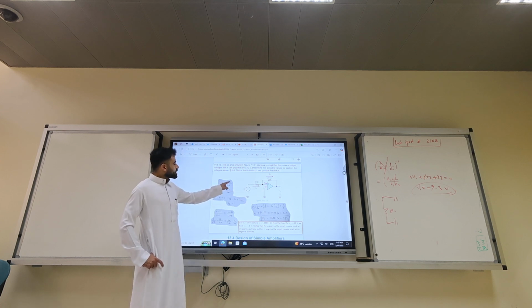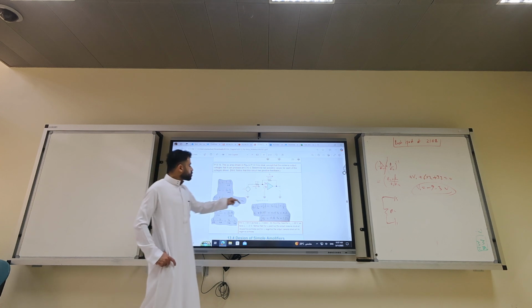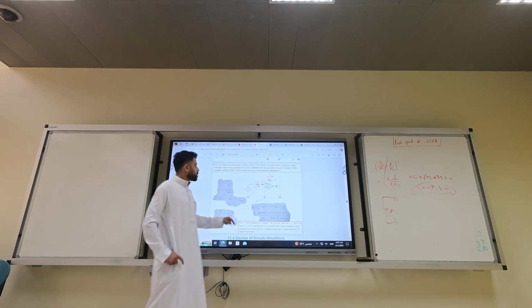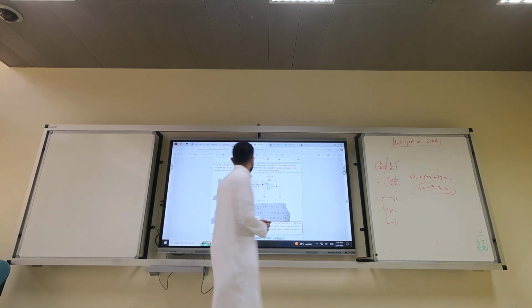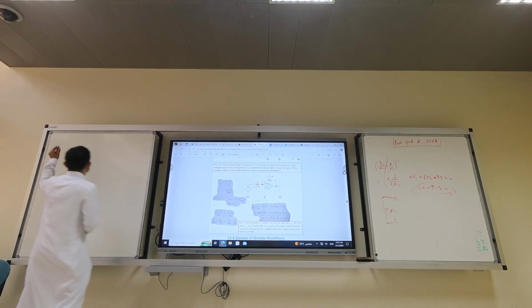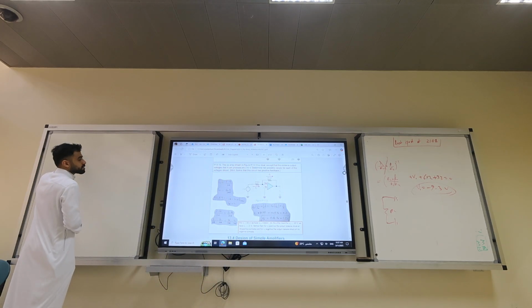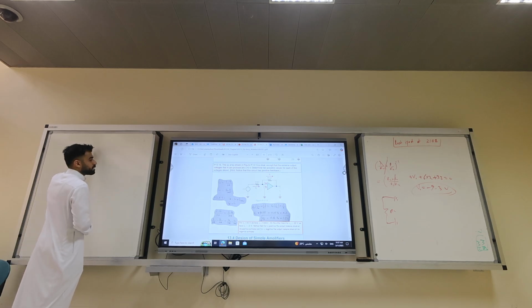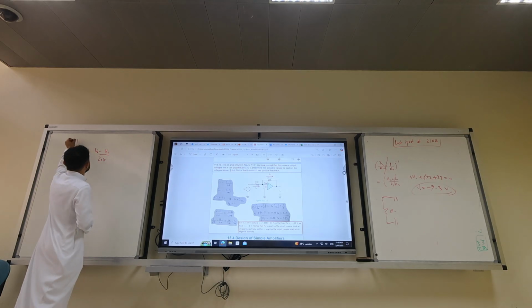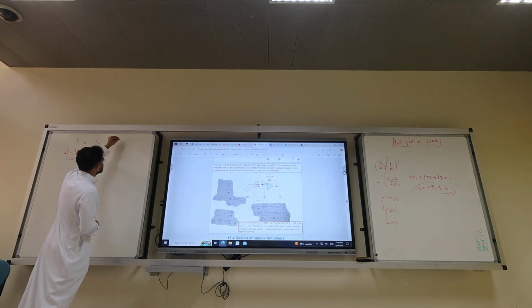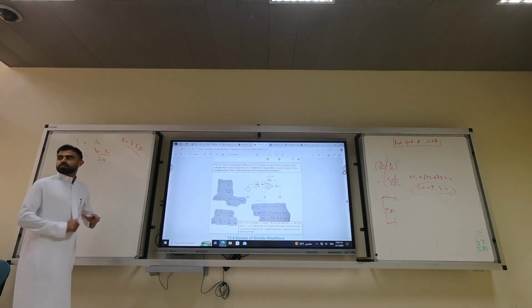So it is 2 minus Vx over 10k, which is equal to I2, which is Vx minus V output over 20k. This is I1 equal to I2. So here, no virtual summing point, VSP.